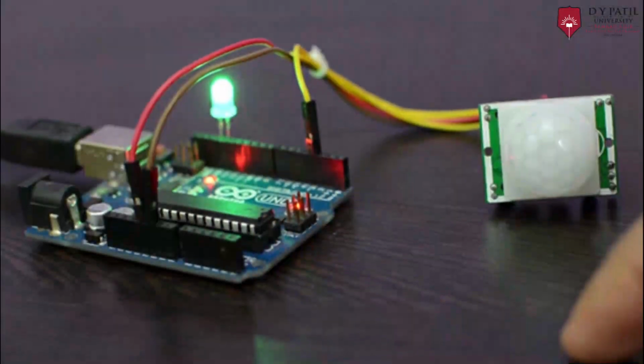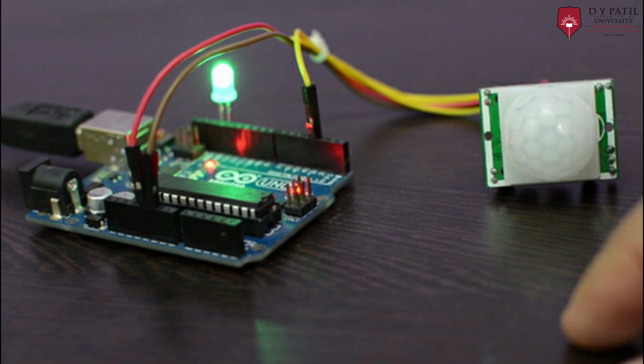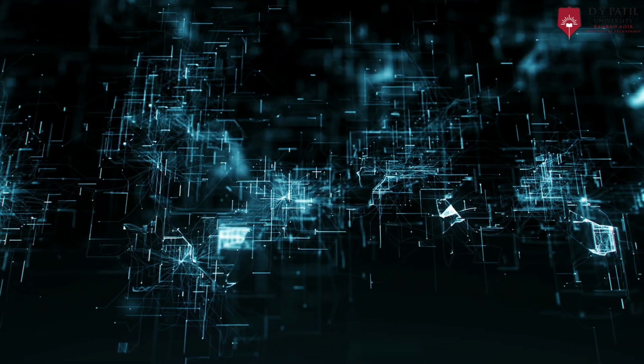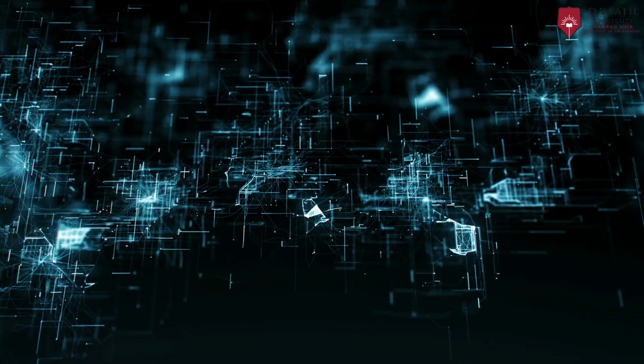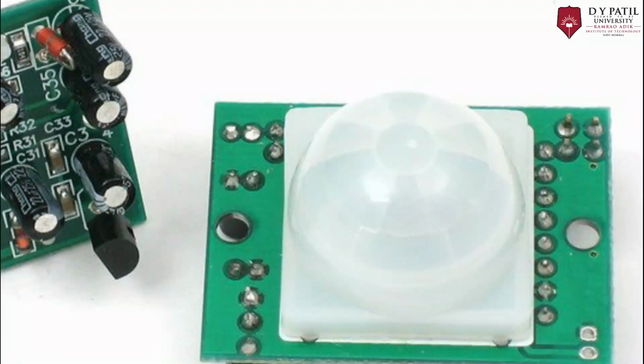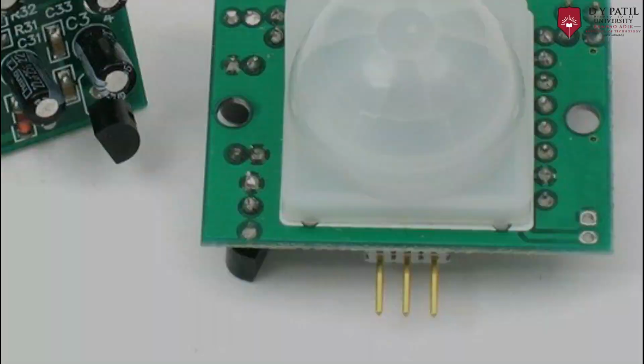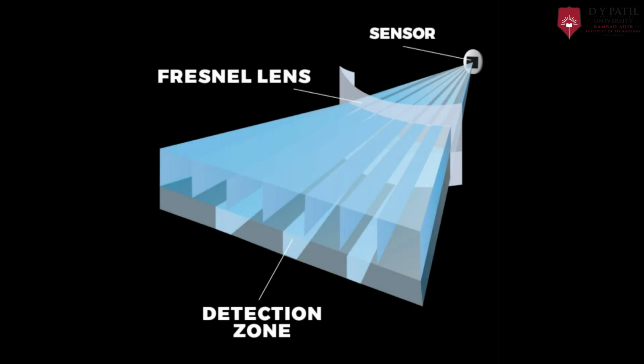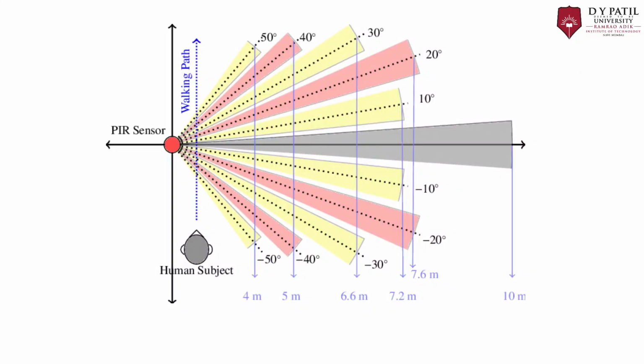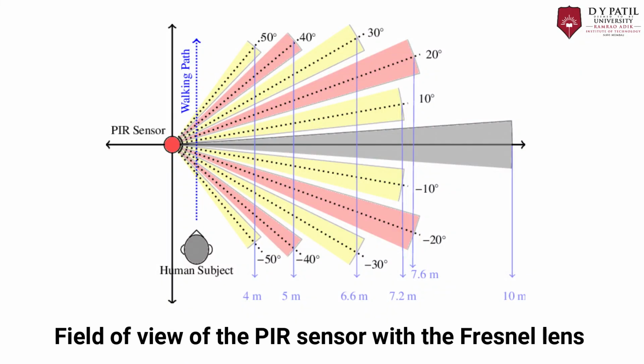A pyroelectric sensor is a type of infrared sensitive heat-based sensor. This helps us to detect the change in motion and not the average IR levels. The white dome on the top of the sensor is a Fresnel lens. A Fresnel lens is a lens that has a surface consisting of a concentric series of simple lens sections. This is used to lengthen the detection distance of the detector.